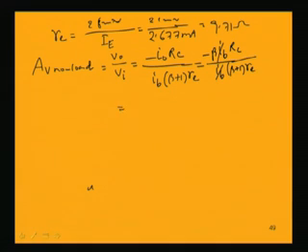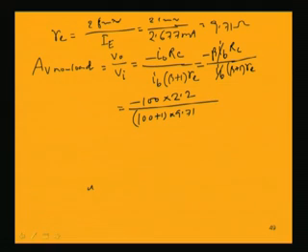So, we get minus beta RC is equal to minus 100, RC is 2.2 K, and beta plus 1 is 100 plus 1, and RE we have found out to be 9.71, but this is in kilo, this is in ohm. So, we have to convert it to kilo ohm, and this gives the value of minus 224.33. Now, this is no load voltage gain.